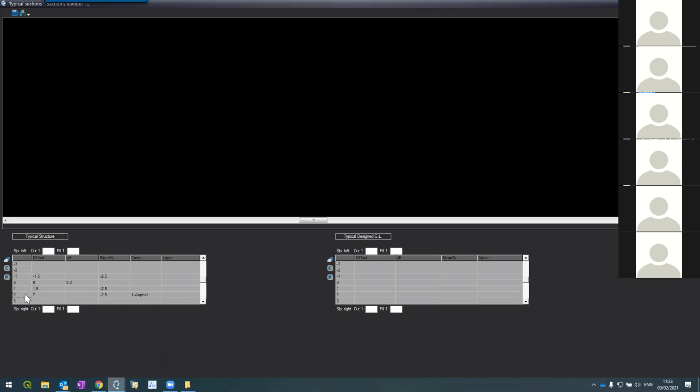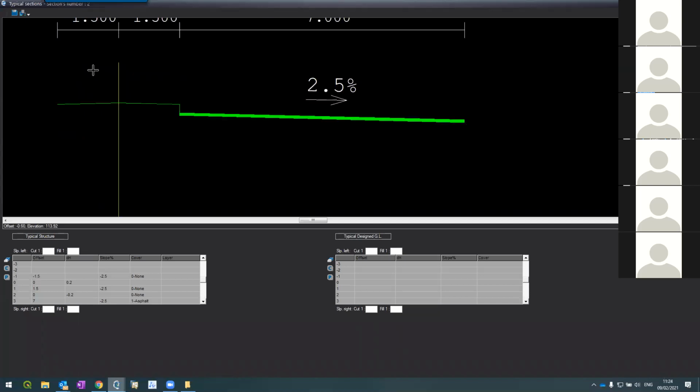It's my mistake because here, how did I open this segment? I stood on the serial number and just pressed enter and went 0, -0.2. Let me show you what I've done so far. I started here. This is the 0, 0. This is the crown level. From here, the median starts 20 centimeters up, goes 2.5%, 1.5 meters, goes down by 0.2 again, and 7 meters like this.